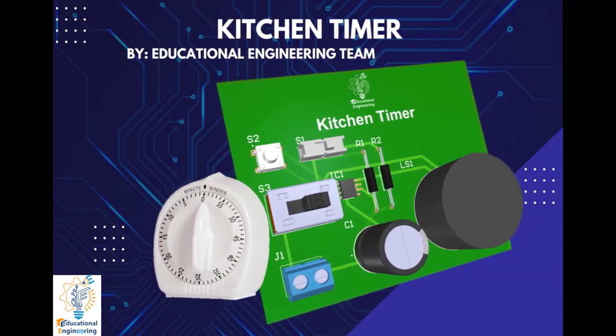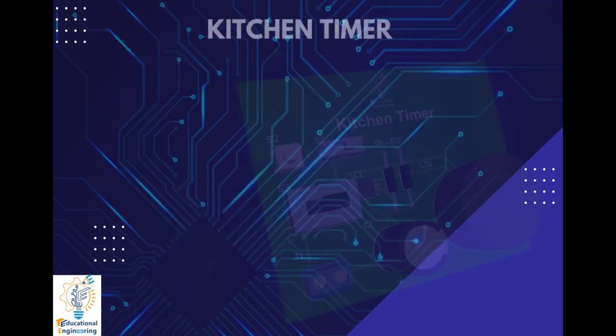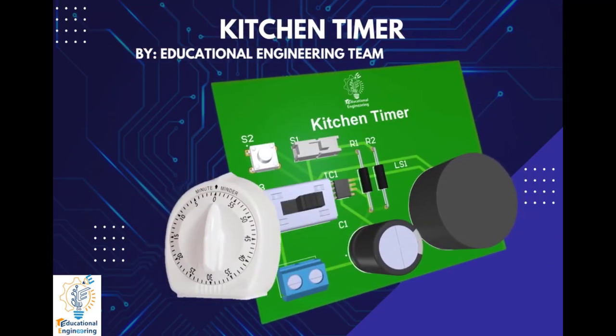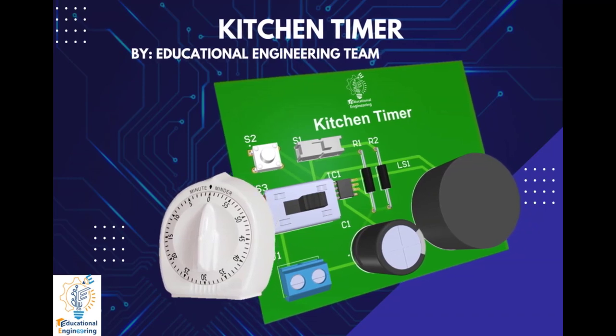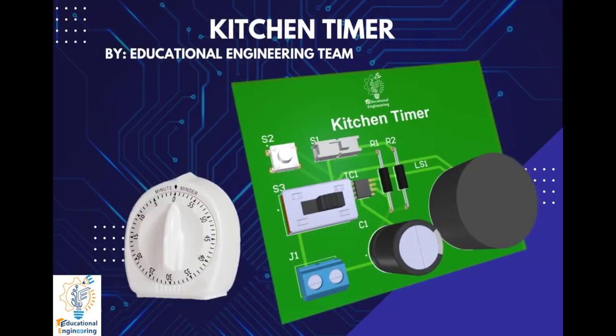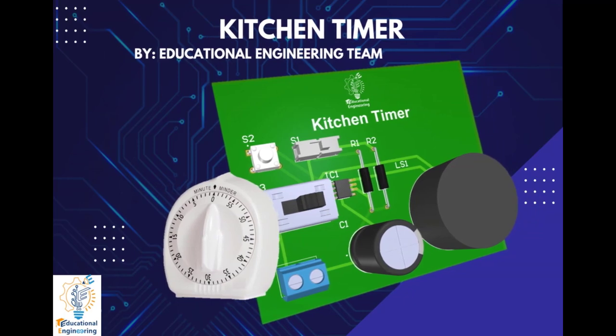Hi, and welcome again to another video. Today, we're gonna learn how to design a simple kitchen timer circuit using Altium Designer. So this board is quite simple and uses a few discrete components to operate. It includes only one resistor, capacitor, switch, a 555 timer IC, and a buzzer.